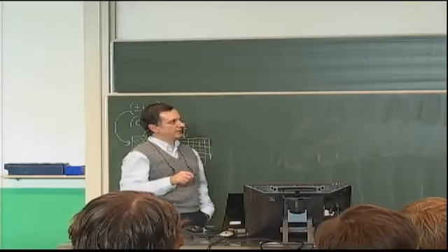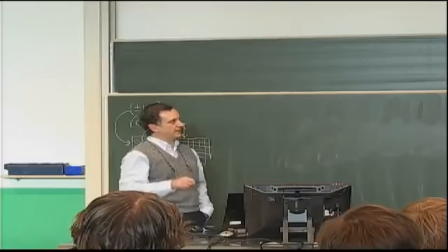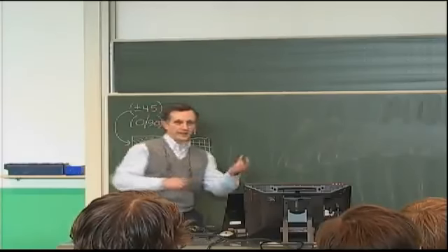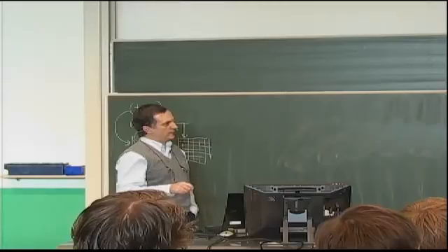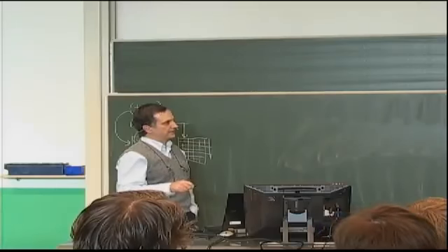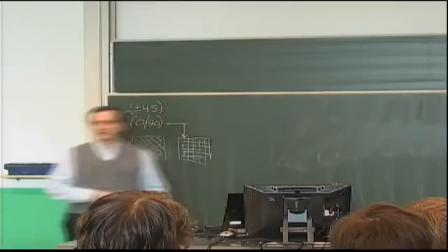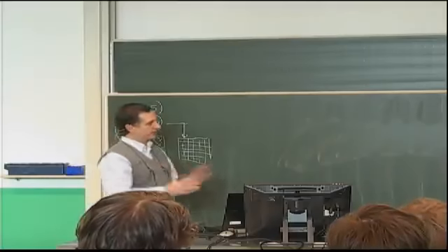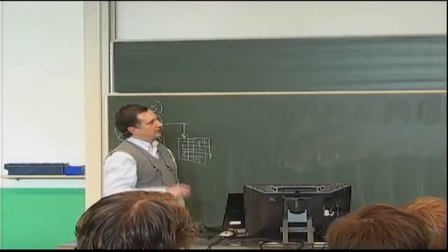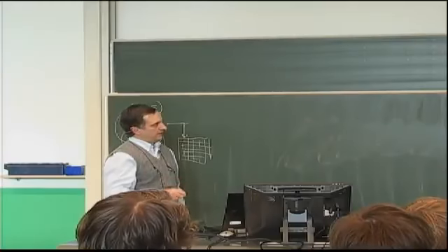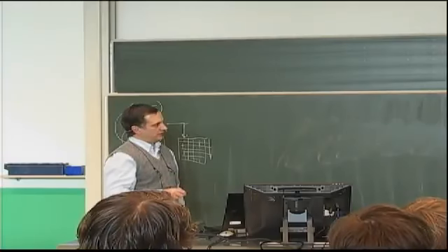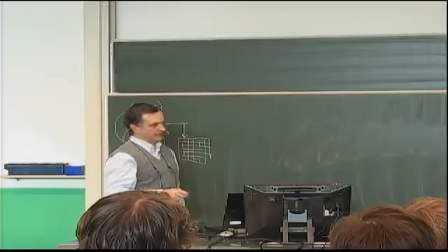Now the plus or minus 45.4 has the highest peak, but it's confined in the narrowest region around the center, while the other two have lower peaks and they again go further out, so they would need larger reinforcement in the y direction. Notice the one that is the narrowest is the plus or minus 45.4, which basically goes to 0 very quickly.